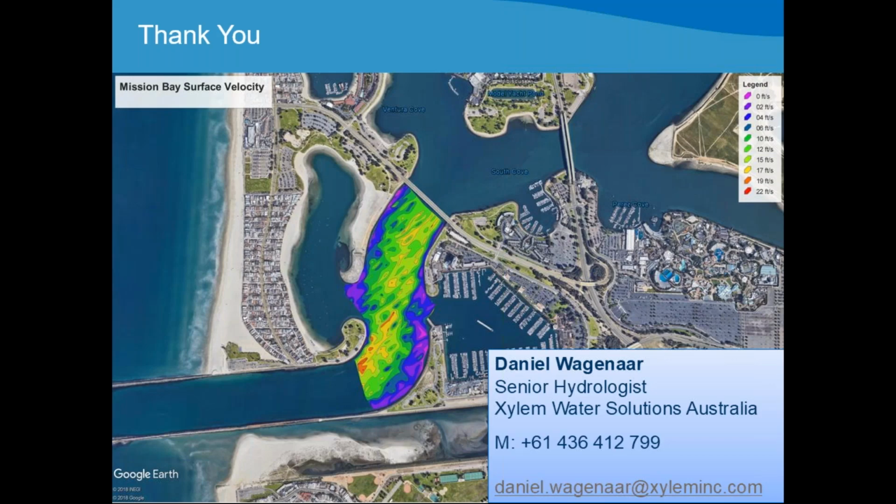If you have debris on the water surface, air bubbles, even, and I've seen cases in the desert where there's a lot of sand on the edges and the wind is blowing, that we get dust, very fine sands, lying on top of the water surface. And that starts to accumulate on top of the transducers. And that will definitely impact your measurements.